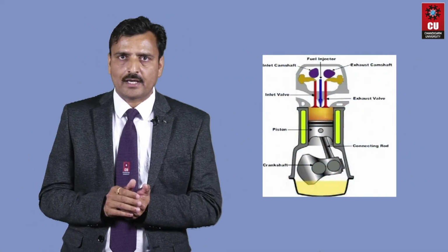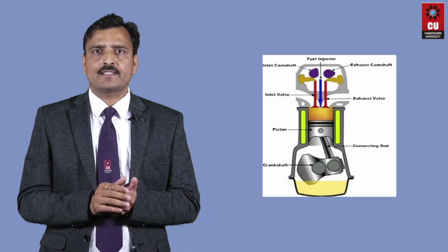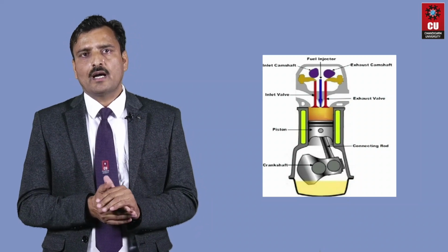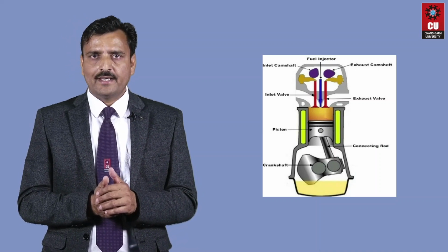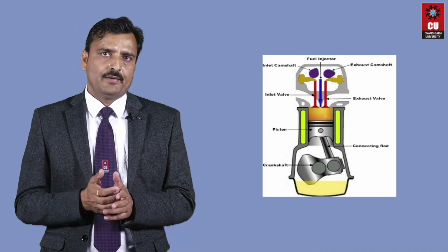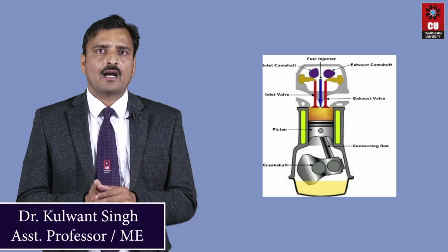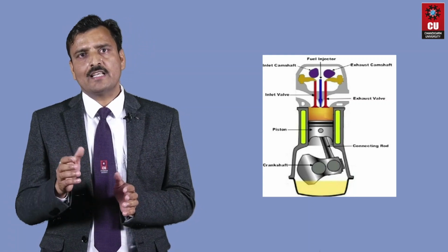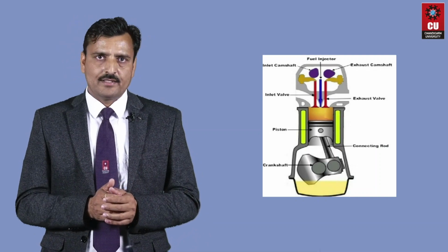The diesel engine is categorized as no spark, and pure air is compressed in the cylinder, achieving sufficient temperature so that after the fuel is injected into the cylinder, it self-ignites. Pressure and temperature in the diesel cylinders are higher than those of the SI engines, as well as the efficiency of the diesel engine is higher than the SI engines.